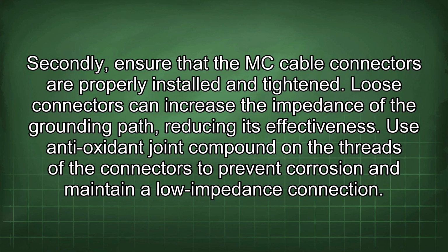Secondly, ensure that the MC cable connectors are properly installed and tightened. Loose connectors can increase the impedance of the grounding path, reducing its effectiveness. Use antioxidant joint compound on the threads of the connectors to prevent corrosion and maintain a low impedance connection.